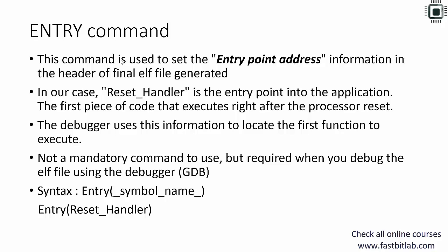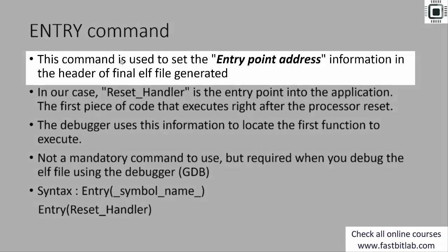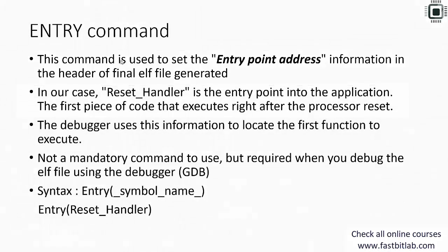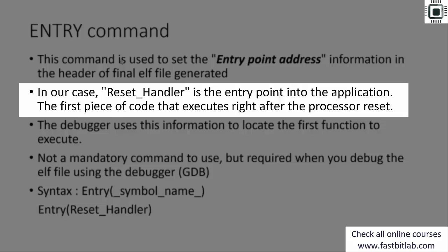First, let's explore the ENTRY command. You use this command to set the entry point address information in the header of the final ELF file generated. What this command does is just populate the entry point address information in the ELF file header. That's it. In our case, the reset handler is the entry point into the application, because that is the first piece of code that executes right after the processor reset, isn't it?